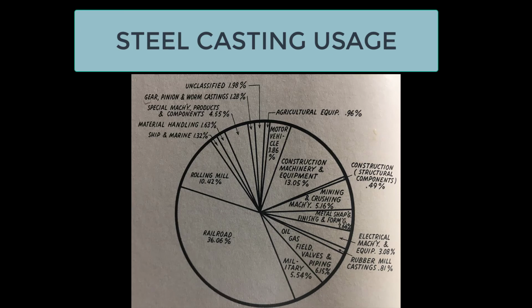The other defects that are very common are porosity, which is the result of gas bubbles, which is the result of an excess of certain things in the molten metal, right? There's certain alloys that you can throw in the ladle before you pour that'll reduce the amount of free gas inside of the molten metal, okay, to reduce porosity.